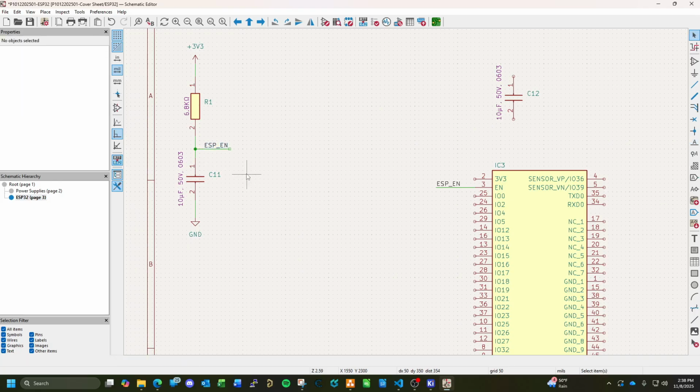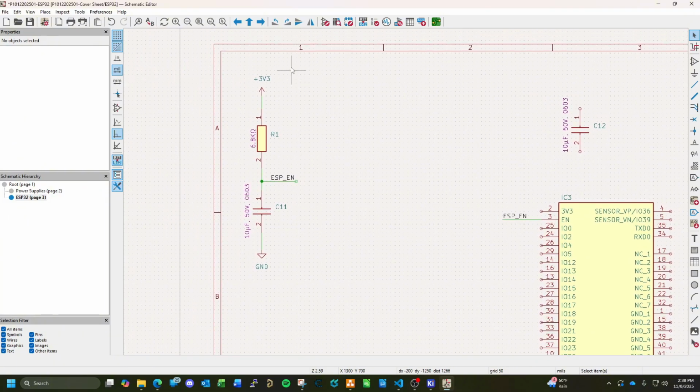So in typical ECAD suites, like Circuit Studio or Altium, you could assign a net label to a wire like this, and internally it will actually connect them when you go to put it on the board. That way you can reduce the complexity of your schematic, so you don't have wire drawings going everywhere. It's supposed to help simplify your schematics and make them a little cleaner and easier to read.